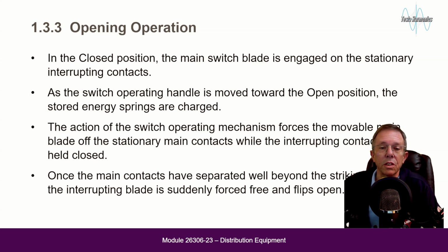The action of the switch operating mechanism forces the movable main blade off the stationary main contacts while the interrupting contacts are held closed. Once the main contacts have separated well beyond the striking distance, the interrupting blade is suddenly forced free and flips open.